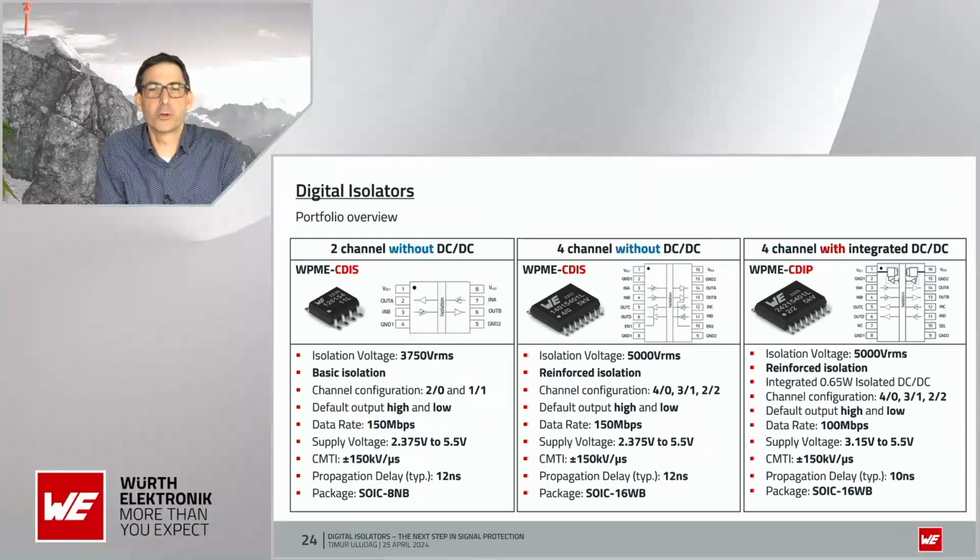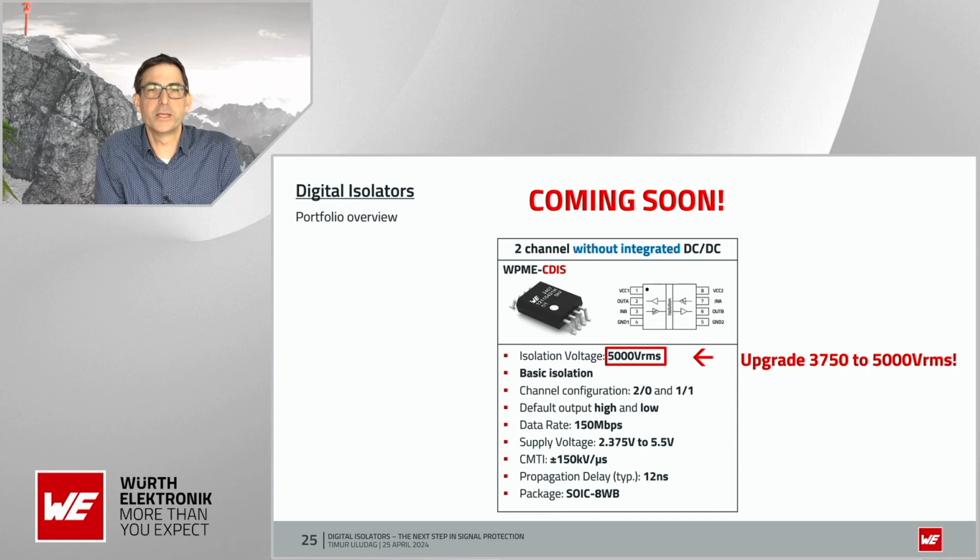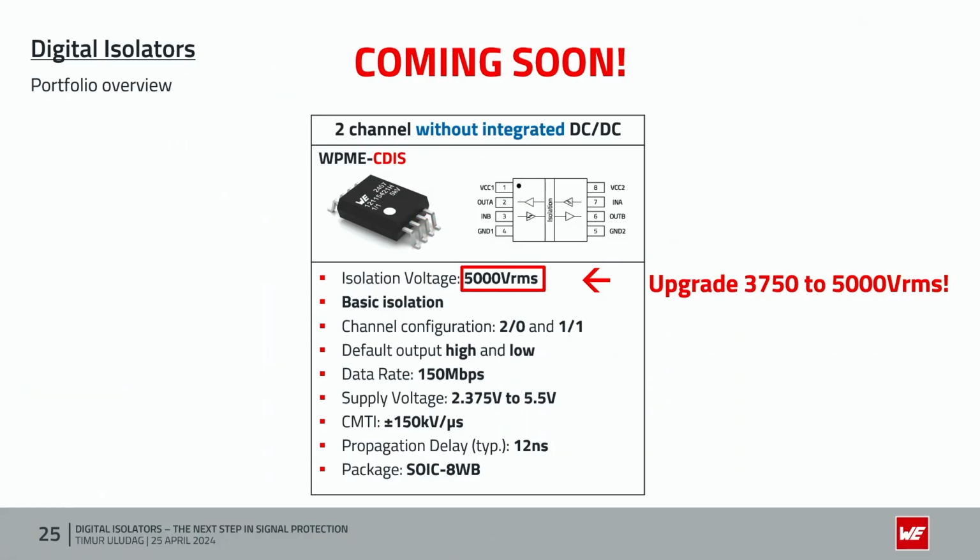Now, a little bit looking into the future, what's coming up next. We will soon expand our portfolio of the SOIC 8 with a SOIC 8 wide body version. That means we can upgrade the isolation voltage from 3750 volts up to 5000 volts RMS, because we have got here a special package where the pins are a little bit wider than the one in the SOIC 8 narrow body package.